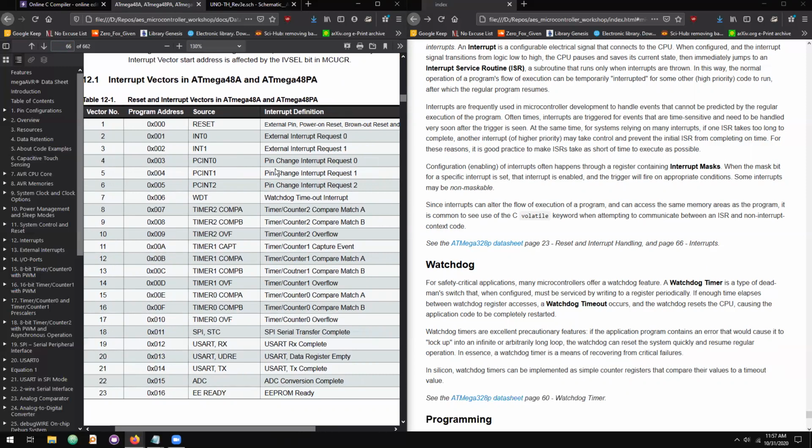So when these are unmasked, let's say INT0. So this is external interrupt request 0. And what this does is for a given input-output pin, if you have a signal on that pin that changes its logic level, you can configure under what conditions this interrupt will fire. But generally, if you detect a transition to logic level high, logic level low, or even on any transition, you can configure this interrupt to fire. And the CPU will know that INT0 is the source, and so it'll fire the INT0 specific handler or interrupt service routine.